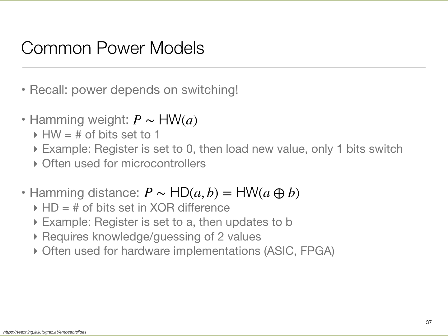Simply eyeballing and fitting things, that kind of simple attack model, whether using these or template traces, is the first order type of attack. There is a more sophisticated attack, which is referred to as differential power analysis. The idea in differential power analysis is that you try to develop immunity to errors or differences that may exist from device to device.